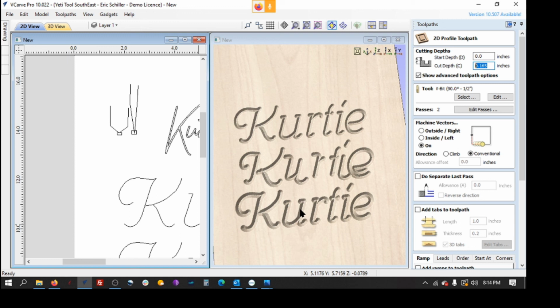He does have a surfacing bit. He just hasn't used it yet, so I'm going to do a separate video probably tomorrow. It's getting late tonight. I'm just beat. I'll do a quick video on how to do surfacing with V-Carve, to do a quick surfacing of a slab. His slabs are 19 by 37-ish, and he can do one, or he can set up multiples and just let it run while he's doing other things. Surfacing is a very quick, painless operation because you don't do a big depth of cut. You just let the machine do its work.